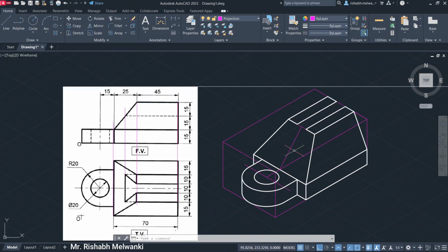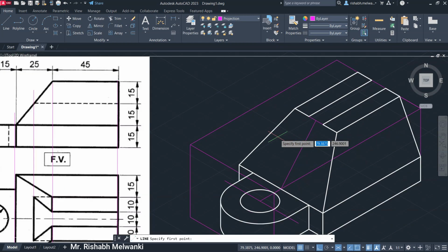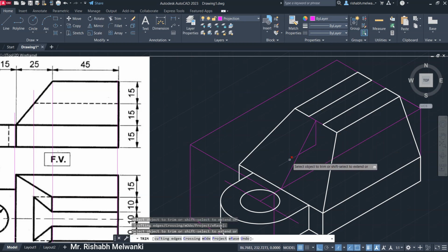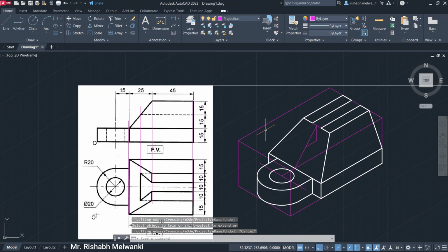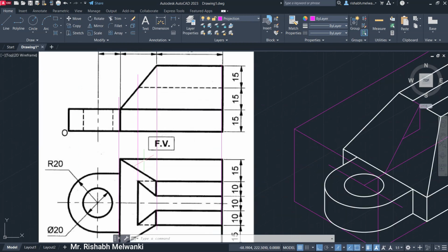Okay, now next we need to move down by 15 millimeters. So again select line. From this point we need to move down. So press F5, 15, enter, and then towards the inclined plane, which is this line. So I'll click over here and trim the excess portion, TR double enter. Now if you see the slot from this point, the slot starts and this distance is not equal.